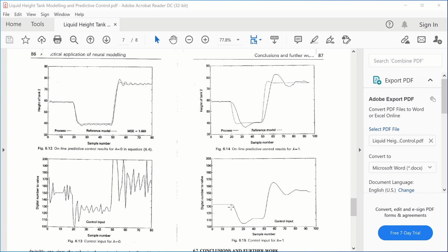All right, so why is it a good neural net application? Non-linear, and you don't have inputs for the first column. Yeah, so he's nailed it. It's not like the distillation column where the system has so many state variables. It's a pretty simple system, but it's non-linear. And they're trying to show that even if they don't measure one of the hidden variables, they can still do the control manipulation. So that's the system. That's the benefits of using a neural net. So that's the other question.